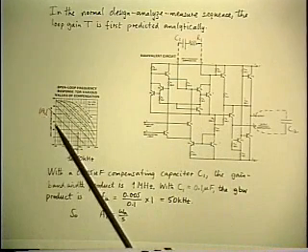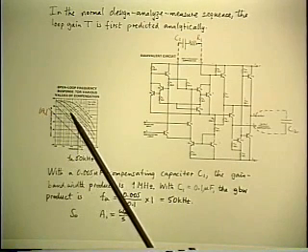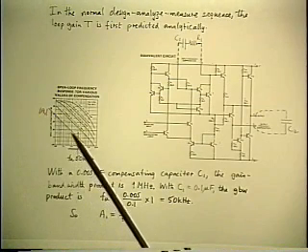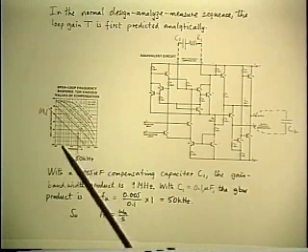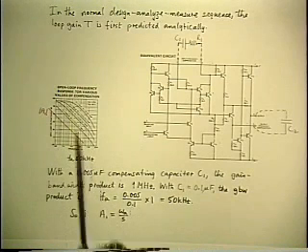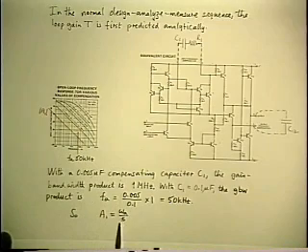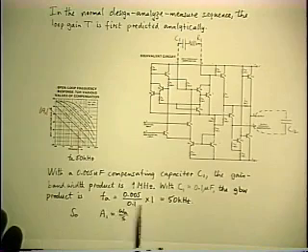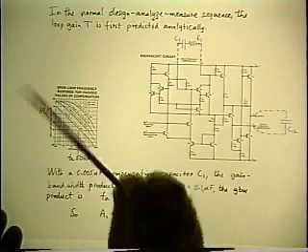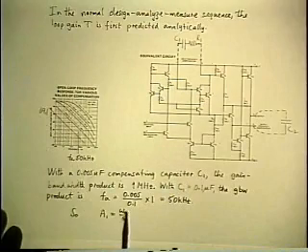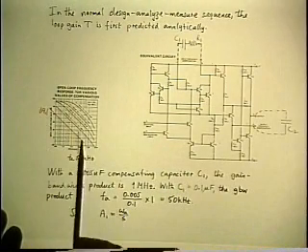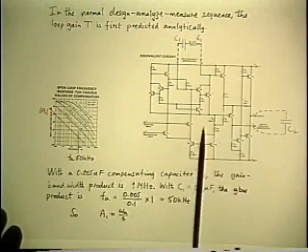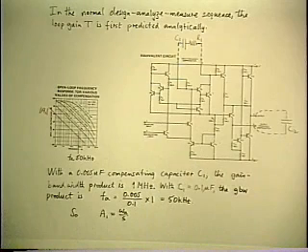So I don't need to write an equation that represents the gain of the op amp all the way down to zero frequency. All I need is an equation that represents this asymptote, which is going to influence things near crossover. And that's the standard single slope that we've done lots of times already. So the expression for the gain of the op amp is simply omega A over S that specifies a declining single slope, and the omega A is the frequency where the magnitude goes through unity. That's the unity gain frequency. That's all I need to represent the gain of the op amp.